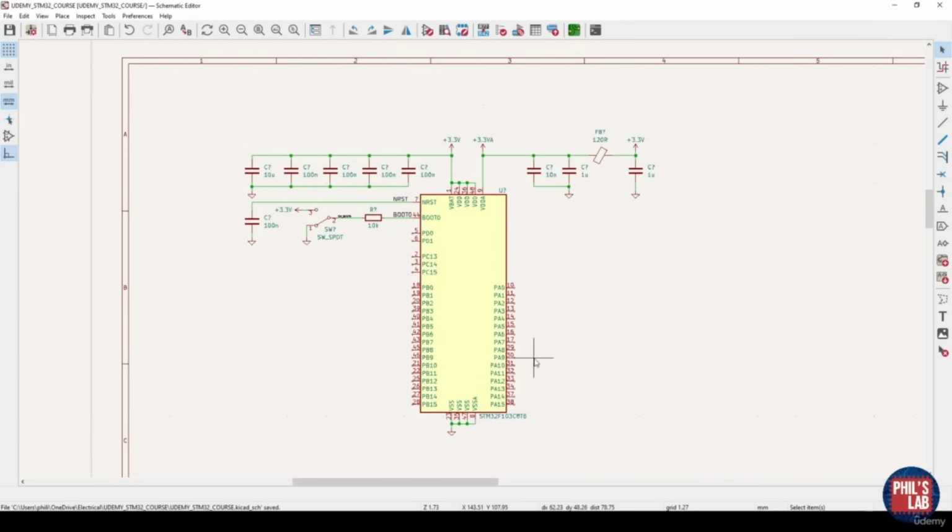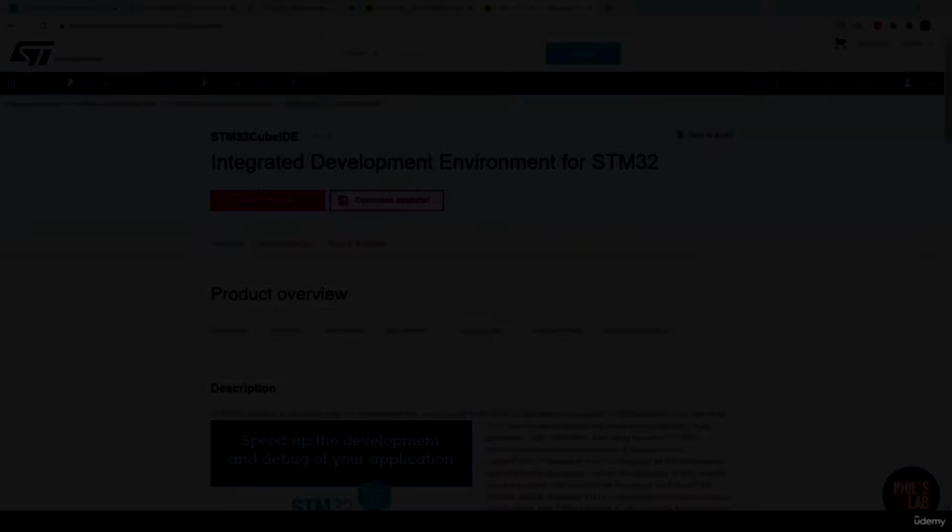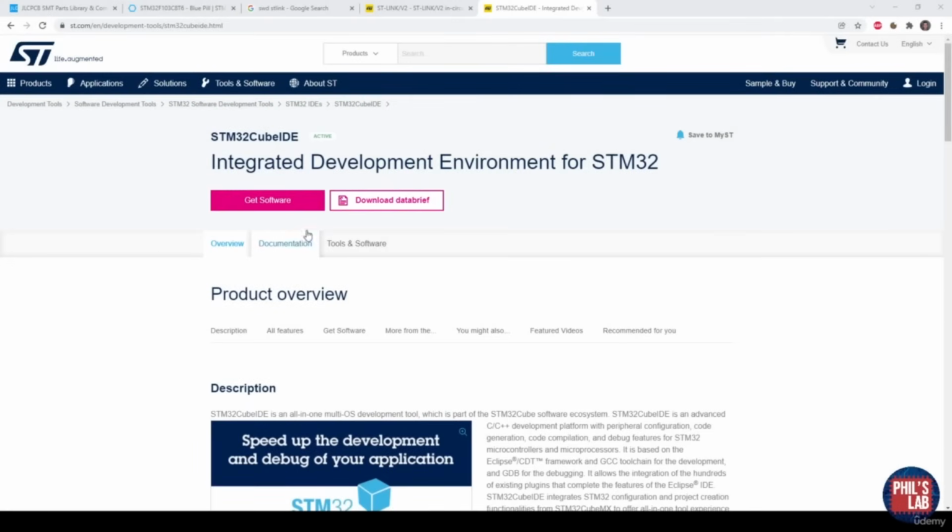We might want to select some sort of pinout, connect UART, SPI, I2C, and so forth. The way we do that is via STM32 IDE, which is also the programming environment. I'd strongly encourage you at this point to download STM32 IDE so you can follow along. Once you have your boards in your hand and you want to program them, this is my preferred way of programming them. So this gives you an Eclipse-based IDE.